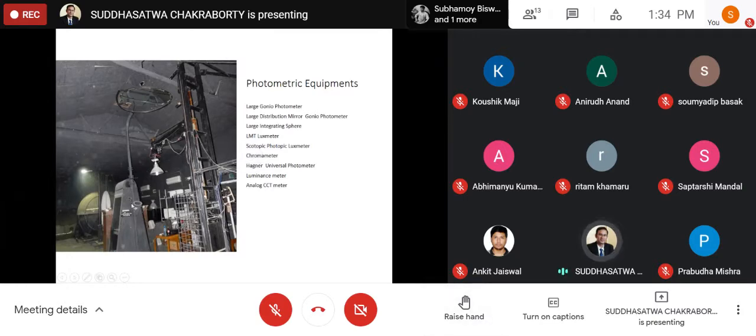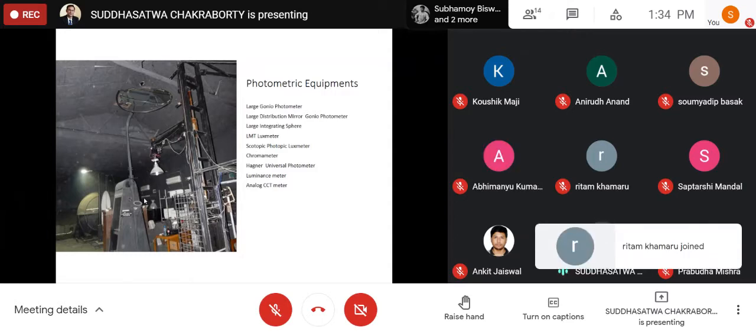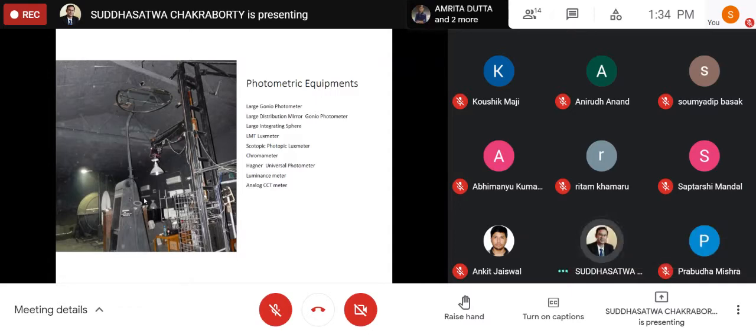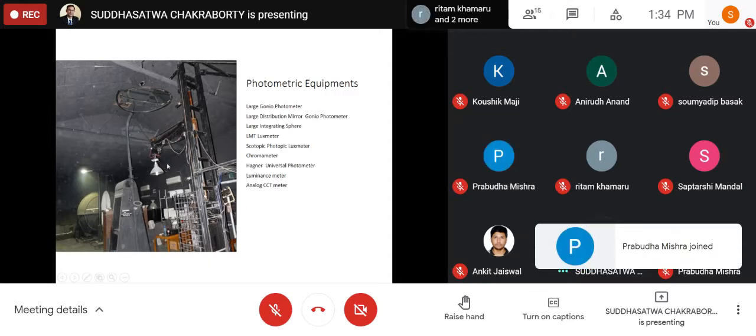So that's why this is a black baffle. It's not a completely hollow baffle. If you see, there are some concentric notches. At the bottommost part, the sensor is mounted just to ensure that no direct light should reach the sensor. If it happens so, the point source realization will be invalid because the distance between the sensor and source is not sufficiently large. That's why we are forcing the light to go to the mirror and then reflect back.